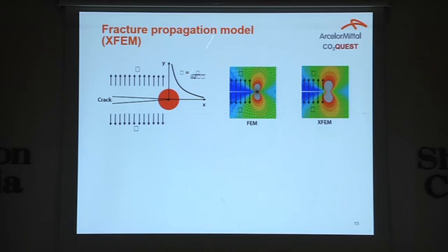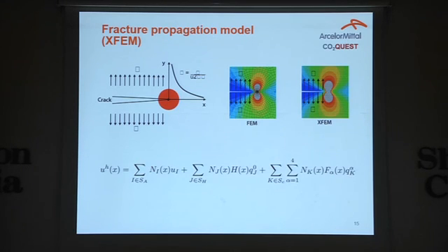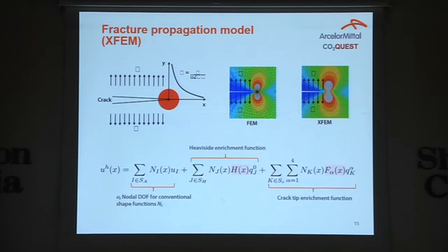So for fracture, we use the XFEM approach. Again, equations are missing. This one not. We have different approaches to capture singularity and also to model crack propagation through the pipe. We need to have, let's say, a cost-effective model, which does not take a lot of time or a lot of memory, because we're coupling with the CFD model, and time is a really important factor here.